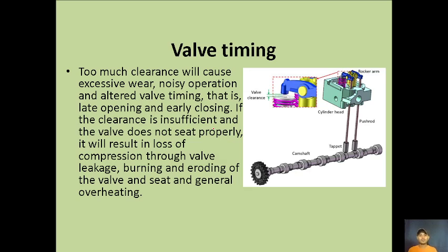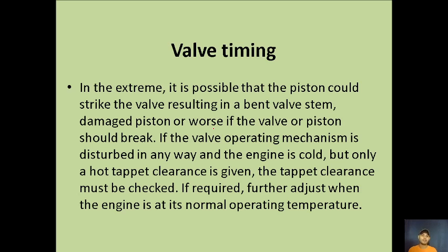So too much clearance will cause excessive wear, noisy operation, and altered valve timing. That is late opening and early closing. If the clearance is insufficient and the valve does not sit properly, it will result in loss of compression through valve leakage, burning and eroding of the valve and seat, and general overheating. In the extreme, it is possible that the piston could strike the valve, resulting in a bent valve system, or damage to your valve, bending or breaking it. So damaged piston, or worse, the valve or piston could break.